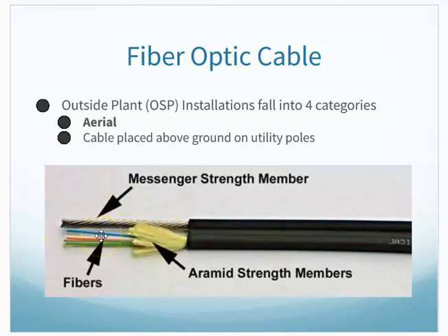If I'm going to install aerially between telephone poles, I'm going to use a cable that usually has a strength member in, like a steel cable here. That's what you're seeing here. This steel cable can get anchored to the telephone poles. That's going to take the weight and support the weight. And this insulation on the outside almost looks like a figure 8. This part down here almost acts like a little hammock to hold the fibers, so the tensile strength is not pulling on the fibers. The cable is taking the weight. The fibers are going along for a ride.